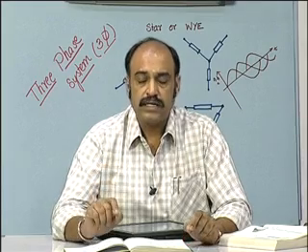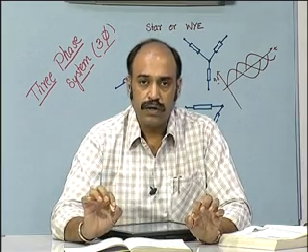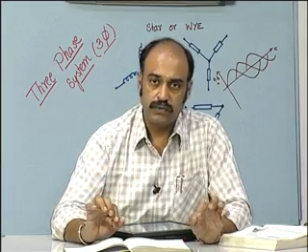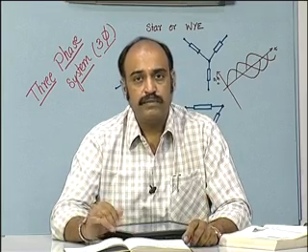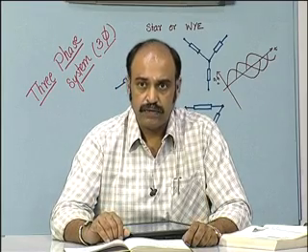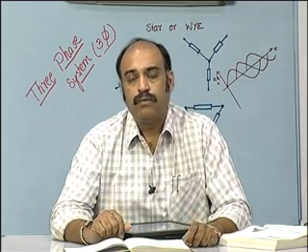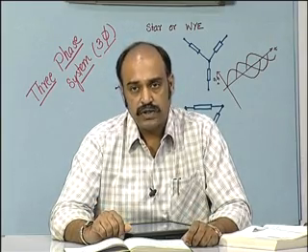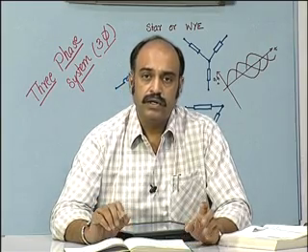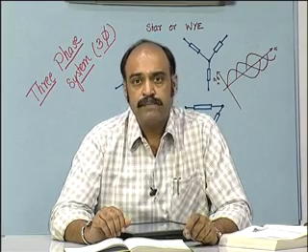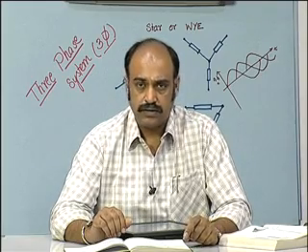Under such conditions the neutral point of the load and the neutral point of the source are connected, and it becomes a 3-phase 4-wire system. Under unbalanced conditions, if the neutral connection is not provided, then there will be distortions in the voltage wave shapes of the 3-phase loads.